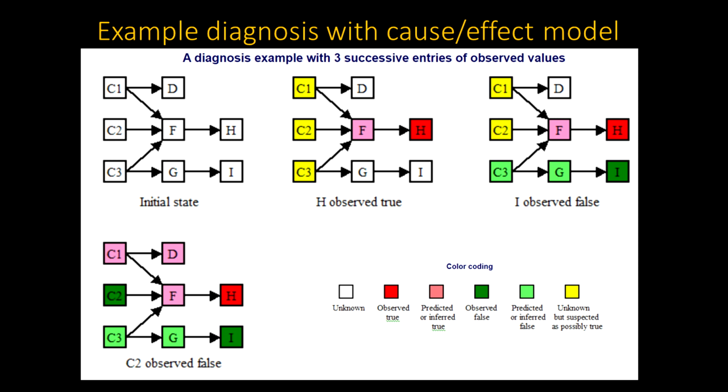And as a side comment, in almost any kind of logic dealing with diagnosis, you have to have unknown as a possible state because there may be sensors that have failed, and maybe you can fix them, maybe you can't. But there may be long periods of time when they're not available, and you really can't know things. So you have to consider really three-valued logic: true, false, and unknown. Also, some of those may represent tests that you don't run on a regular basis, and you only run them when you need to help differentiate between a couple of different possible faults.